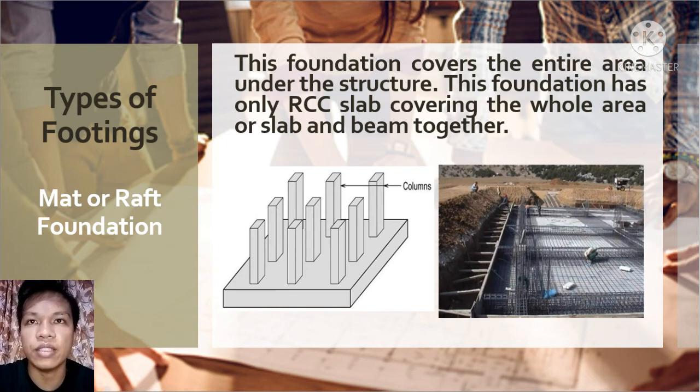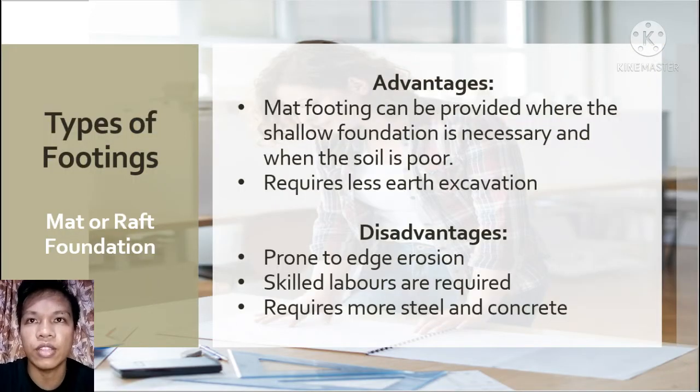These are the advantages of mat foundation. Mat footing can be provided where a shallow foundation is necessary and when the soil is poor. Mat foundation requires less earth excavation. They are a fast form of construction with minimal excavation and are sometimes also used on small clays as an alternative to the reinforced wide strip foundation.